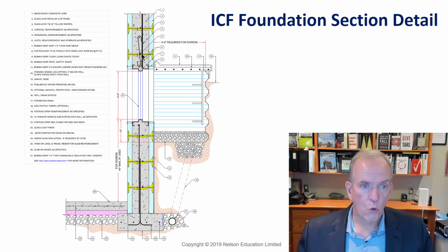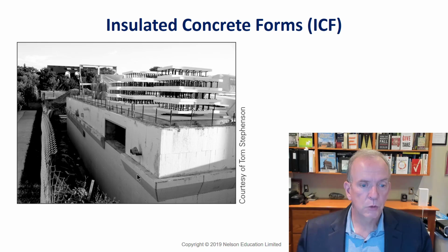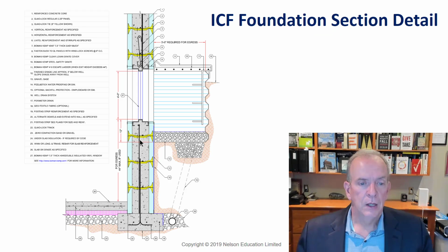These separators hold the styrofoam at the proper spacing, and you can screw drywall to them on the inside. You can even have ledges built into it to support brickwork like this has here. So the brickwork would go up above that. So you want to talk about a very well insulated wall that is totally soundproof other than the windows.